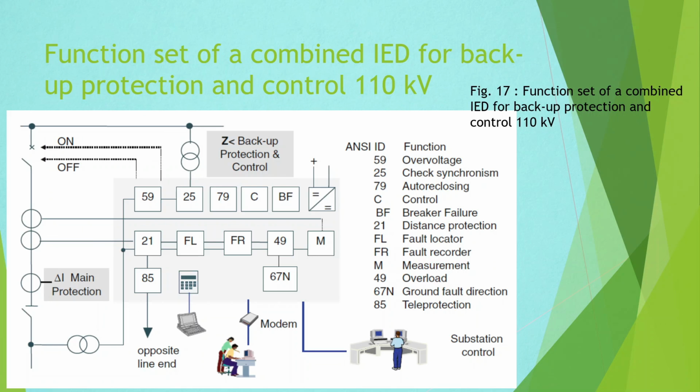This method ensures that the switching does not endanger the stability of the network and is also used in combination with the auto-reclosing. Resonant neutral grounding is partially used in 110 kV networks.